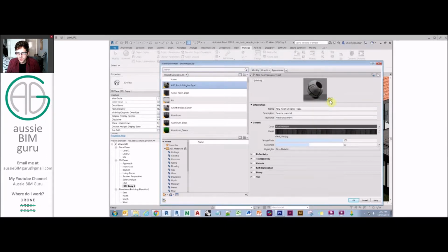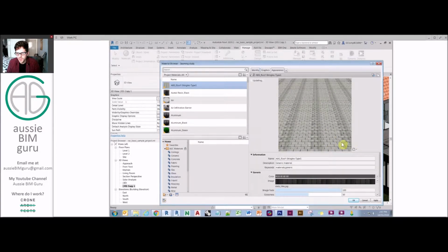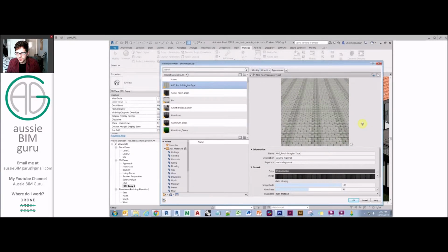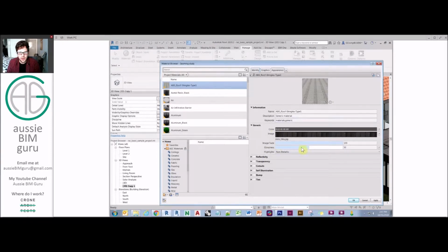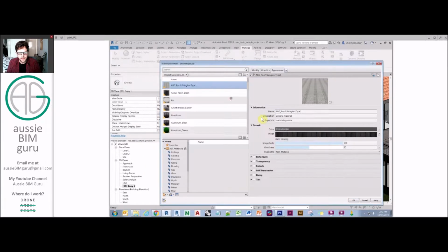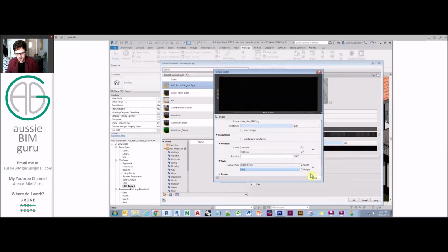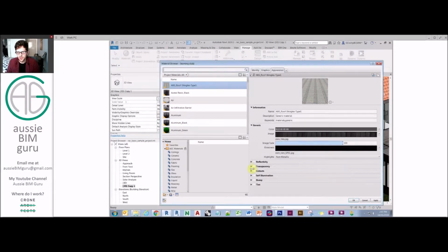So now it should be much larger, and we can change the scene that we're looking at it in as well. And there you go. So you can see that the seaming's not incredible in this material. It is a little bit too obvious in some areas what's happening, but that's okay. It should do for now. We'll load up a gloss map as well to our specular, and we'll make sure that's also scaled at the same ratio. So every map needs to be coincident in scale.